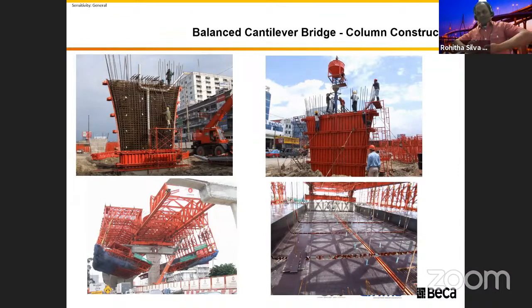After the bridge construction, the concrete cast, we do the post-tensioning and everything. We lift the gantry like that. You can see this arm. We move it hydraulically. It's not rocket science. It's just the way you hold your hands together and open up. That's the same thing we employ in here. This is a piece of your hand. It opens up in here, and then make sure it opens up and pushes. It will move across. The principle we use in this moving across is like a seesaw.